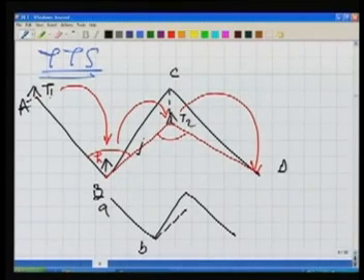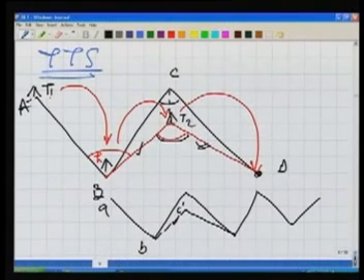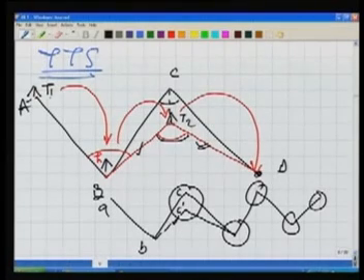Then I measure this distance, plot this distance, and I get the point C dash. Now at point C dash I plot this angle, not this angle. By plotting this angle and this distance, I reach point D, and then henceforth the rest of the traverse. So what do we see here? Even if there is a miscentering error here, C has gone to C dash, there is no shift in D. Similarly, there will be no shift in other points. So by doing this TTS, the three tripod system, the miscentering error can be limited to a particular point.